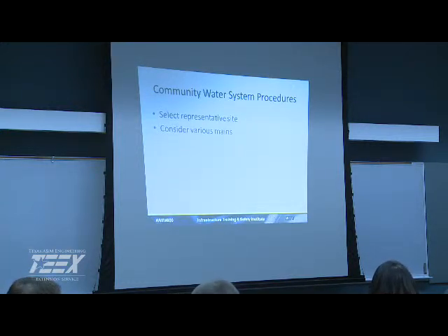We started talking about valving in the distribution system. You start having water quality issues, and it turns out those guys were out there working on it, and I bet they didn't open that valve back up. Or they valved off a dead-end, low-population area, put in a big main expecting all this new growth out there, and it doesn't come for years.